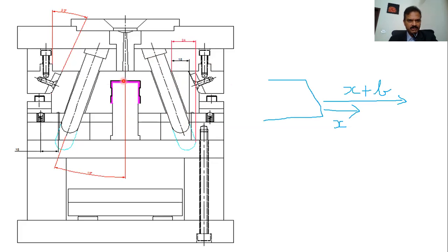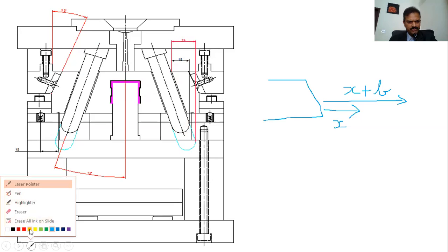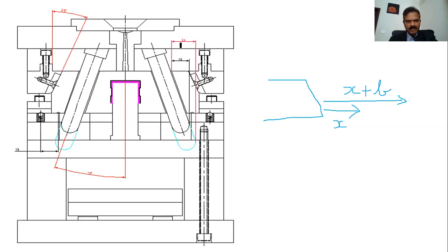It's just common sense. You have a component of 30 millimeter, so per side it is like 15 millimeter. It should cover more than 15 millimeter, right? So in this case, it is designed for at least a movement of 18 millimeter. So if you want a longer movement, you just increase the length of the finger cam. That means it will give, in this case, for example, you see an extra movement of like 24 millimeter, right? If you had designed it to this length.